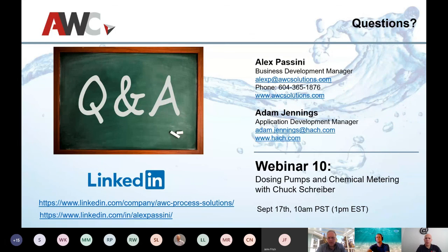Question. Go ahead, Troy. Yeah, hi, Adam. Great presentation. Question of the day is on that probe that you've got on the RAS line on the secondary clarifier, how accurate is that? And can you translate that into a really good mixed liquor concentration? One of the things I've seen in a lot of plants is operators struggling to get a return that has a consistent RAS flow, due to flows and temperatures and whatnot. But one of the issues is getting air back into it. How accurate can you get that mixed liquor on that TSS probe?